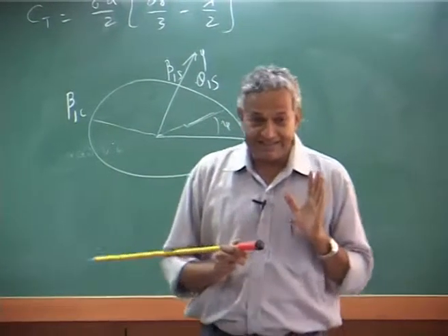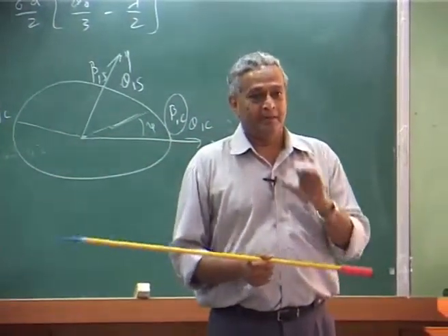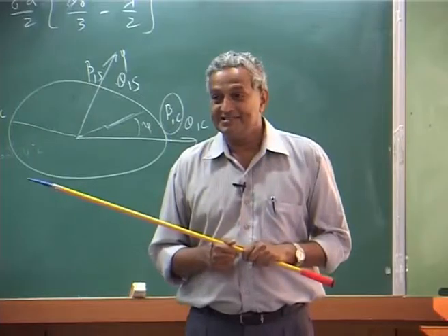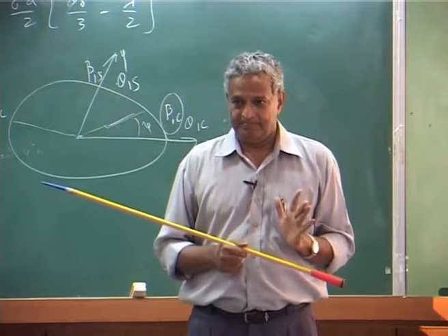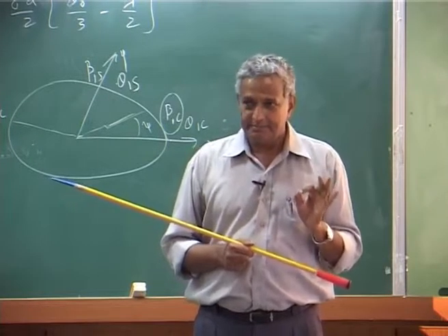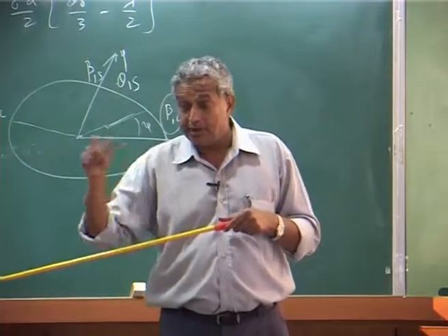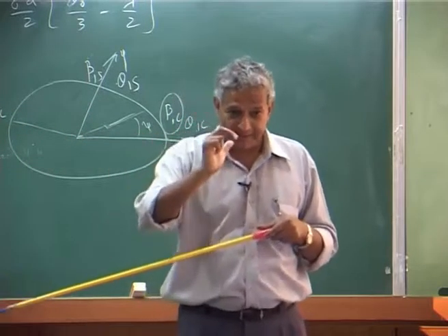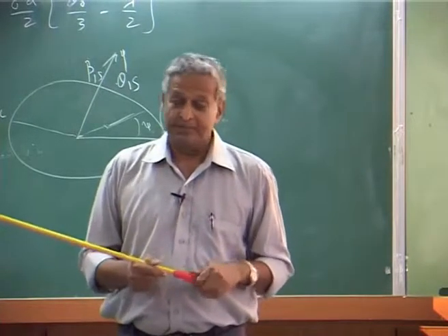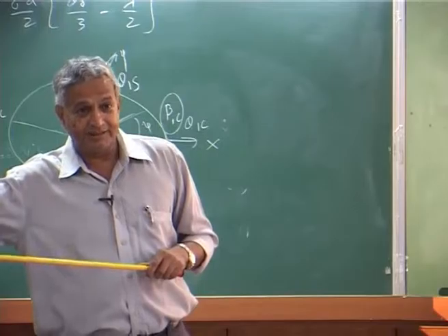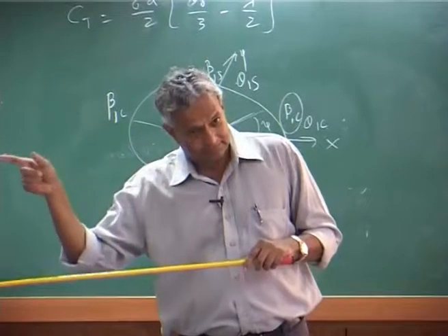But please note, this 90 degree is only for this simple case of hover plus centrally hinged blade. It will vary the moment I have a different flap model. If I put a spring, it will not be 90 degree, it will change. If I put something else, hinge offset and a spring, it will change.